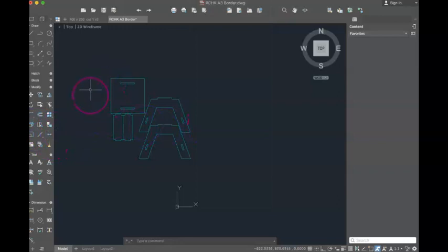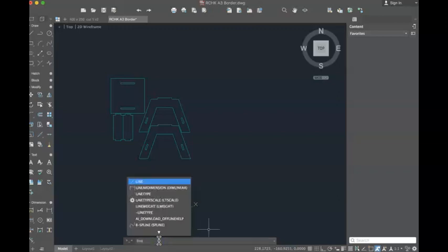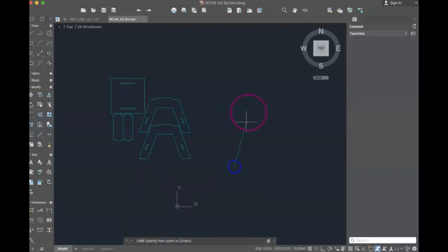A lot of people who are working in AutoCAD in industry will turn all this off because they'll use shortcuts and hand keystrokes, and that's the beauty of AutoCAD, because it's very different to other programs. Once you start using AutoCAD and become better at it, you'll wonder why Word and Excel and other software packages don't use this same thing, because you can communicate with AutoCAD straight through the command prompt box. So if I type in here line, or L for line, it will ask where do you want to draw a line from. These are the things that AutoCAD can do because it has this command prompt box.